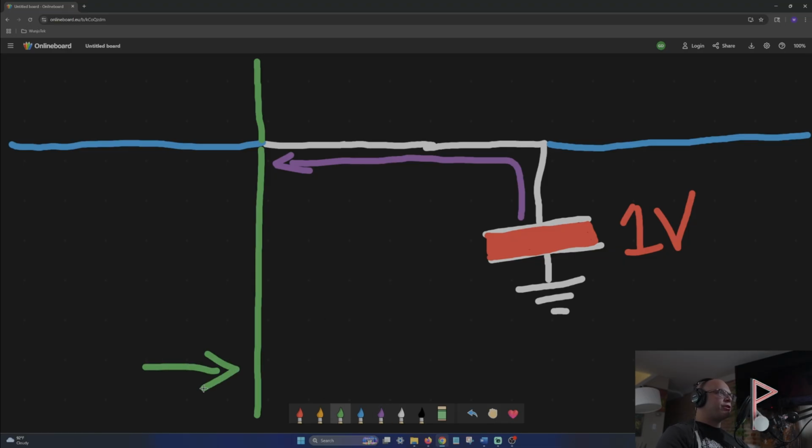is to pre-charge this bit line to right around 0.5 volts. Why does it do that? So that it can detect the change in capacitance. So this bit line is now carrying 0.5 volts. But we've closed this transistor because the word line has been asserted, and part of that 1 volt is leaking over here and hitting this bit line.